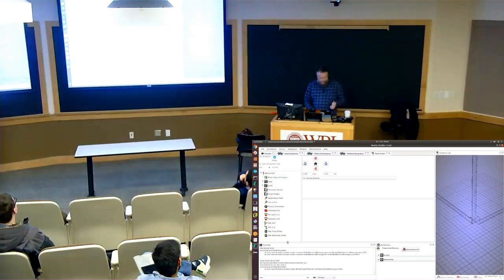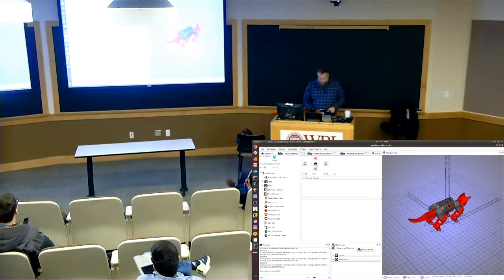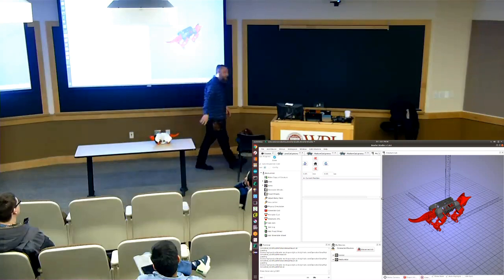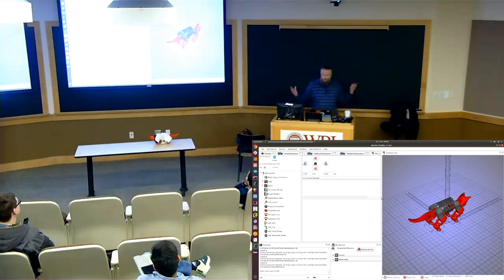The way the two halves find each other is that BowlerStudio sends out a UDP broadcast. The cat has an ESP32 in it, but no control logic whatsoever. Just an ESP32 server that has two things. A servo server, where it says, I have these servos, and you can tell me what position to put them in. And it says it has a built-in IMU, and it sends back floating point data of the Euler angle pose of the robot. This is all well and good, but let's make it walk.